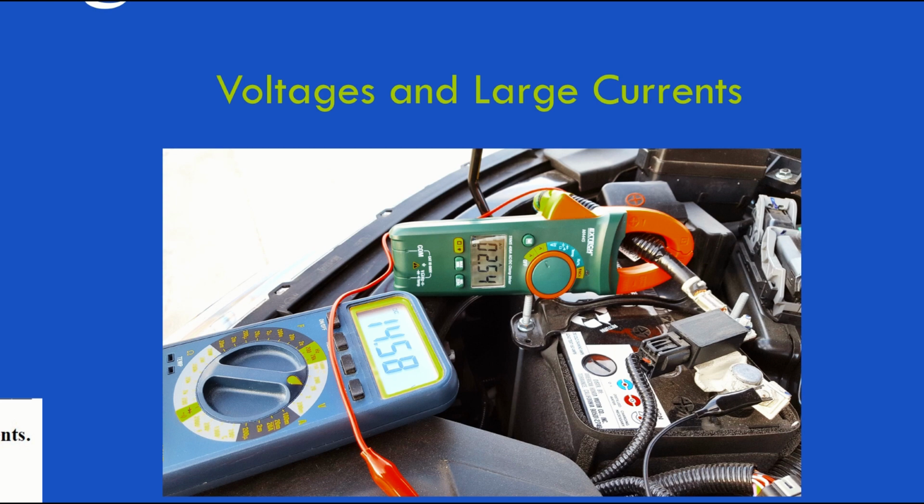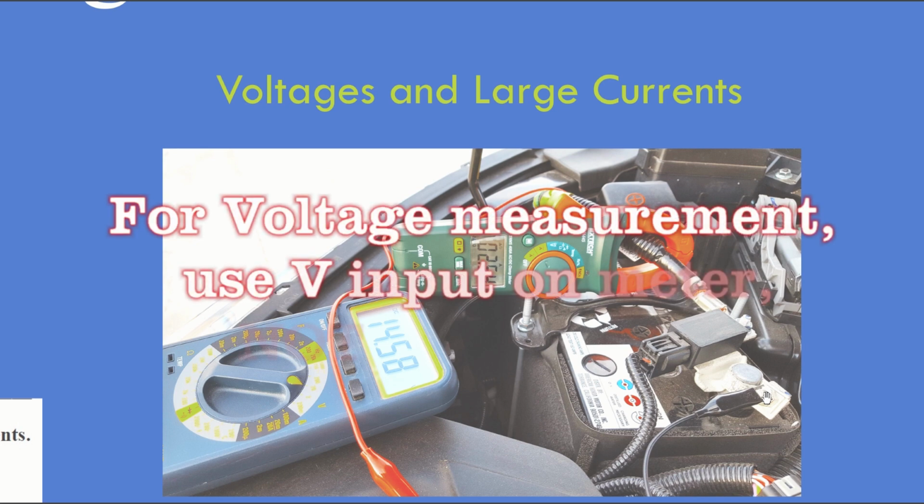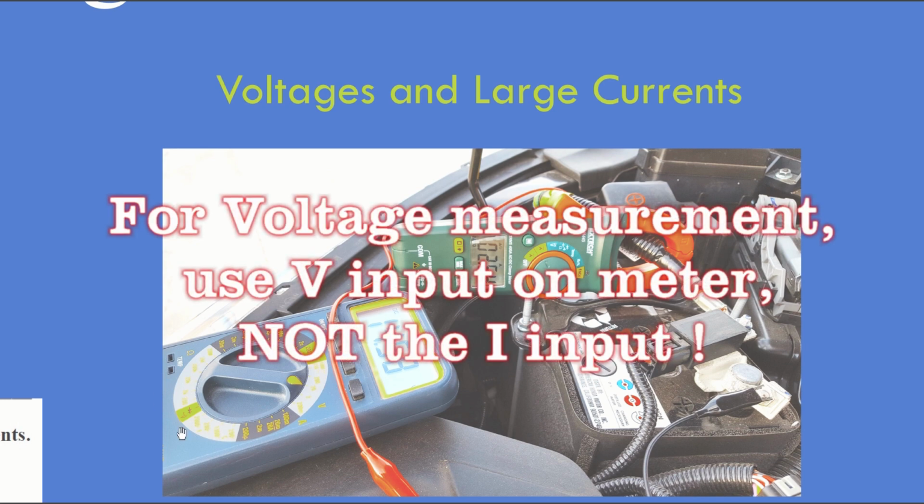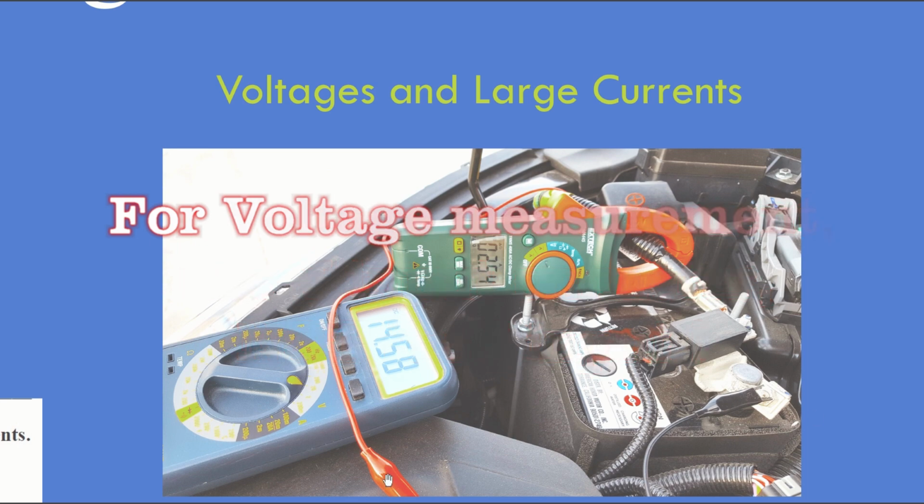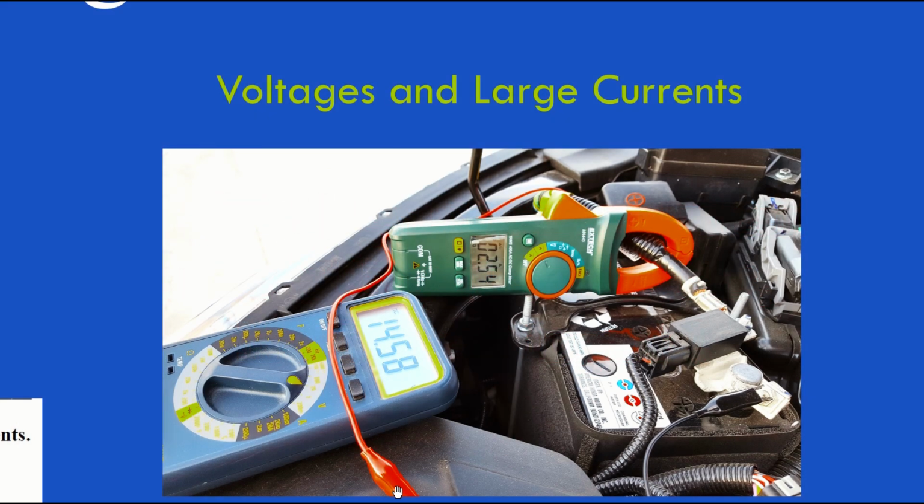And that's because the car is on and it's currently charging. Now, what about voltage? Well, that's what this meter is measuring. There are some leads not shown over here on the left, but you can see the wires. The red wire goes to the positive terminal of the battery, and the black wire goes to the negative. So we're attaching this meter, what's called across the battery terminals. And of course, they're insulated so that we're not touching the circuits.